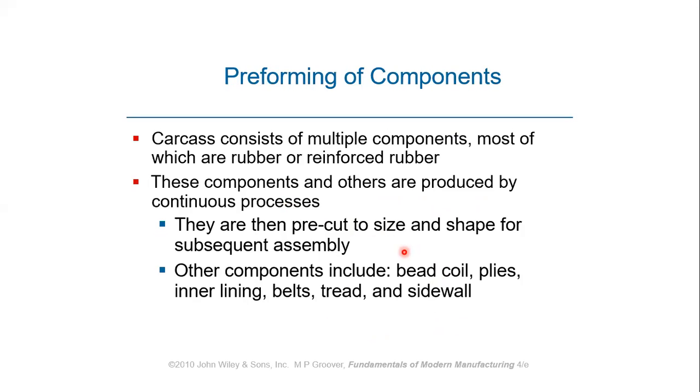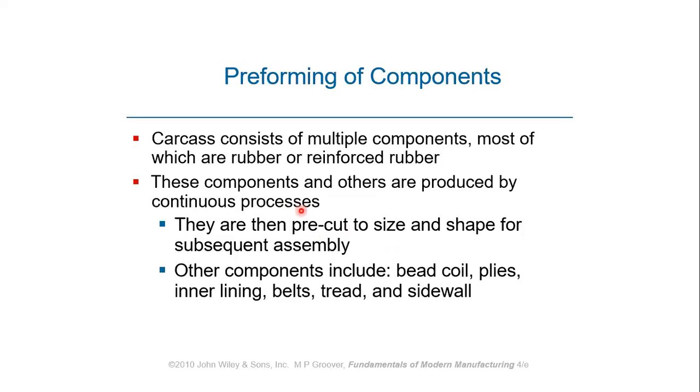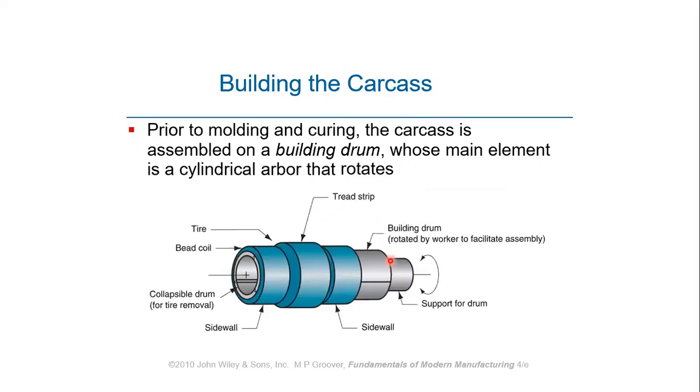The preforming actually involves manufacturing fiber reinforced composite. Actually, I'll show you this. In preforming, different layers of the rubbers of the tire are manufactured separately. That is actually the summary. If you summarize this, different parts are manufactured and cut into size, whatever the size you need to manufacture the tire. You cut them up into required size, and then you stack them up in a support drum.